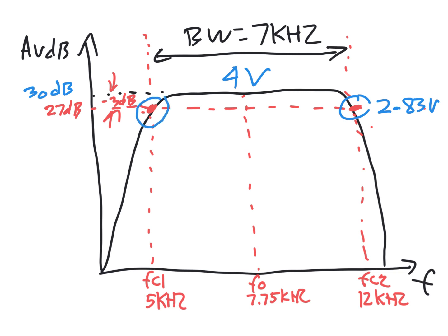Okay, so to determine then, the voltage here is 4. When you decrease the frequency, it falls to 2.8. You're at FC1. Bring the frequency back up, goes back to 4 volts, increase it, falls to 2.8, you're at FC2. So it's very easy to determine that. So just one more. We won't sketch this one, but just throw some numbers.